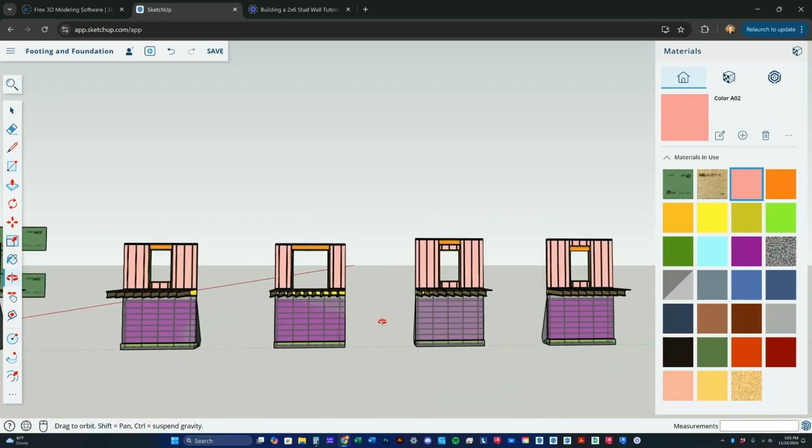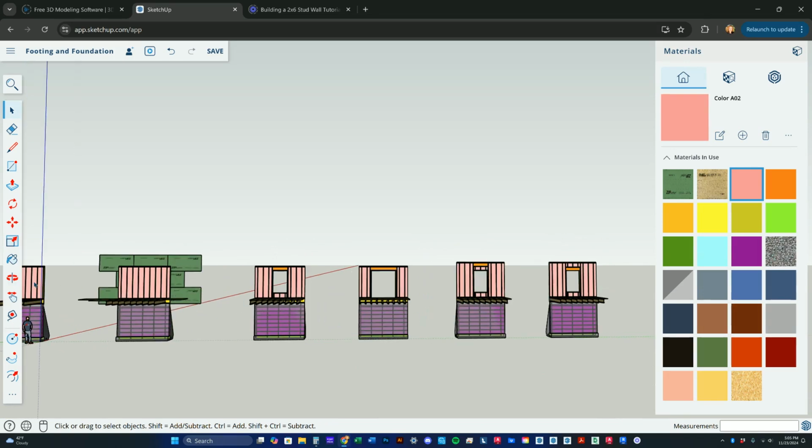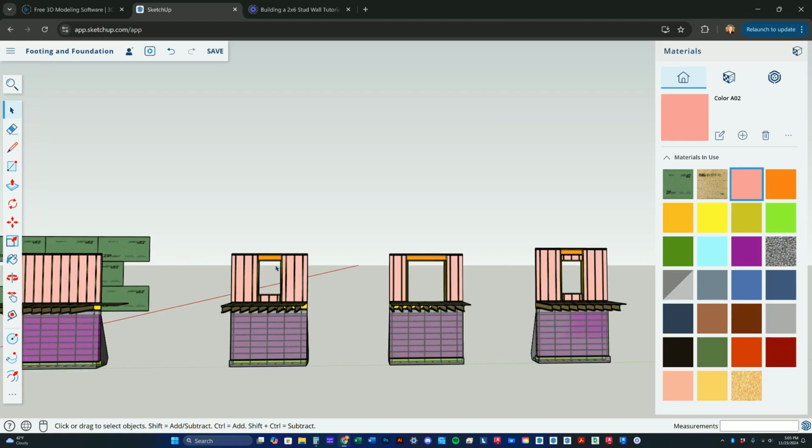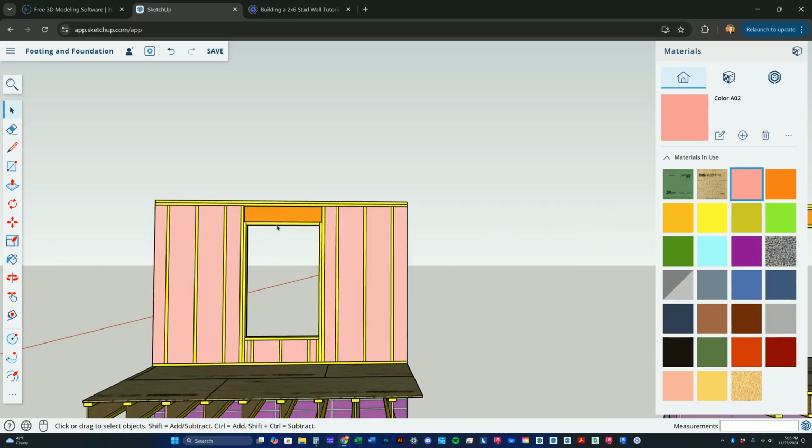So you should have all of these in your final assignment. You have your stud wall. This was me showing you about the sheathing. This is your window with single jack, single king. You're shimming down to 6'10" above the floor and putting in your 1 3/4 by 9.5 inch LVL, laminated veneer lumber header.